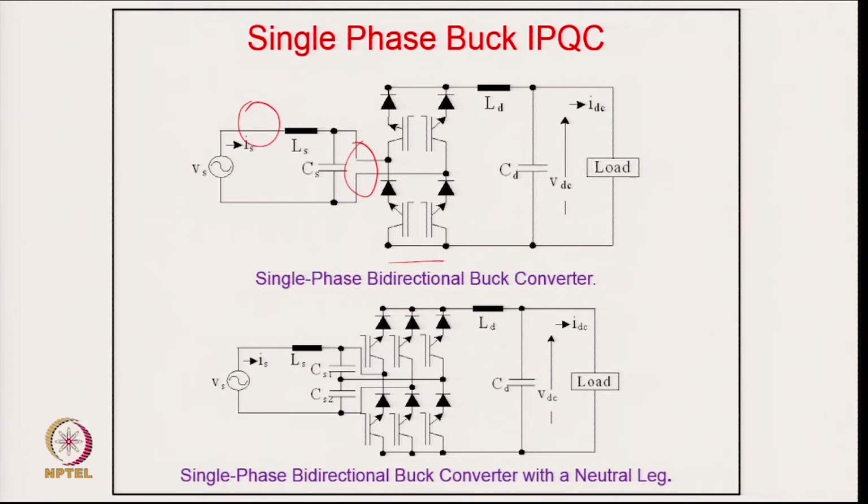And when you have a PWM current, it means you are going to have a current from 0 to the current corresponding to the DC link current, which can be a part of your load current flowing in the inductor. So, this current will be a segment of the output current. When any diagonal switches are on, this current will be a function of the input current, and when you want to make the current 0, then you have a freewheeling action, where you switch on both the devices of the same leg. This is an interesting feature here, and that will give you a freewheeling action.